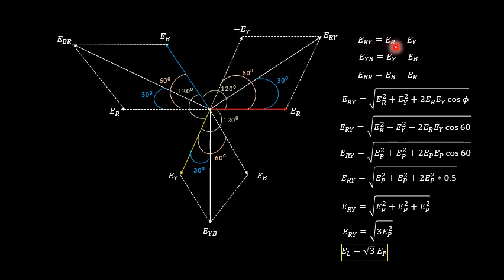So what is ERY? ERY is ER minus EY. EY is nothing but this yellow color line. So I want minus EY in this particular expression, so I am supposed to draw a line opposite to that yellow color line. The opposite direction of this yellow line is towards the top portion. If this becomes EY, obviously the opposite line should be represented in terms of negation, that is minus EY. I am having the ER line as it is because it is positive in this expression. So ER line minus EY will give us a line voltage ERY.